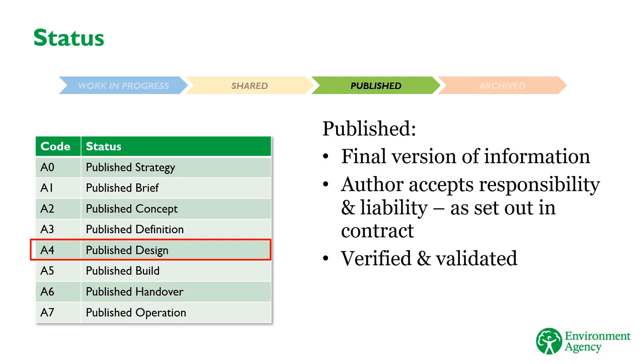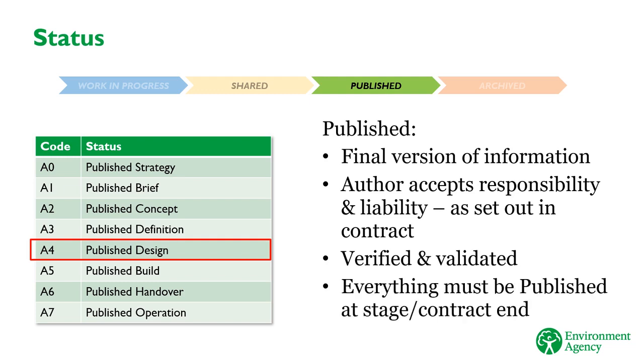Because published signifies that something is at a final state, by the end of a stage or contract, all the information and data within that stage or contract must be uploaded to the E-CDE with a published status and a published code that's appropriate to the project stage.